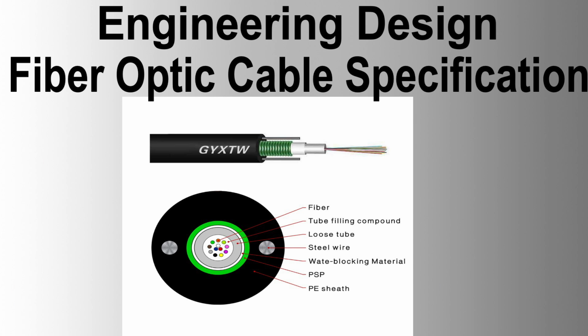Specific tests carried out by the vendor shall include attenuation measurements for each fiber in dB/km, average and maximum, in all cable lengths of the supplied lot. Backscattering diagrams. General inspection, ensuring construction conformance. Fiber-specific tests: attenuation coefficient at 1550 nanometers, non-zero chromatic dispersion slope, chromatic dispersion at 1550 nanometers.